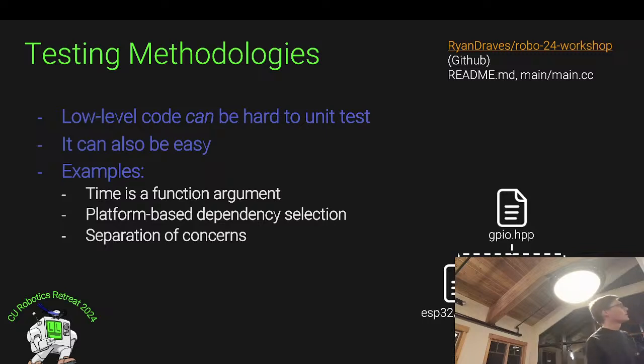But on the compilation side, the implementation of that might defer to two different files. If I want to target my microcontroller, I might compile for the ESP32 in that implementation. But if I want to run a host unit test, I might mock it out and have some host implementation that does some mocked out version of that pin interaction. And part of that idea is this sort of separation of concerns, right? If I abstract what a GPIO is doing, then my driver doesn't need to know about how to use a GPIO. It just knows what methods are available to use it.